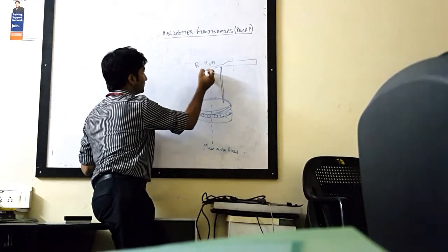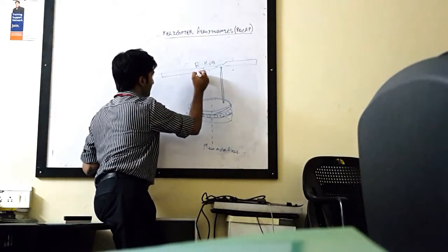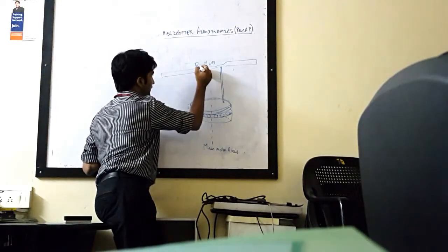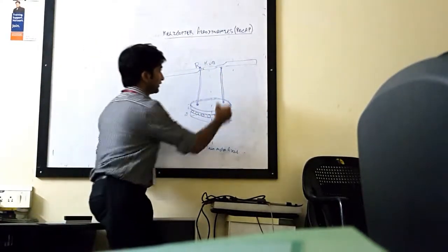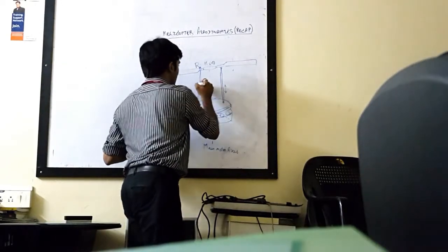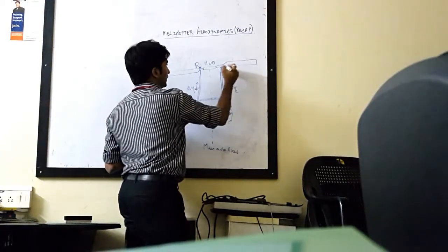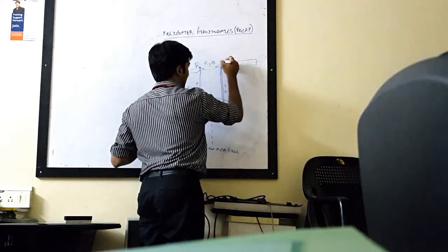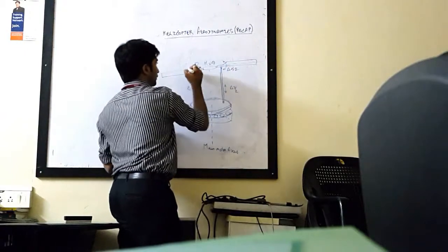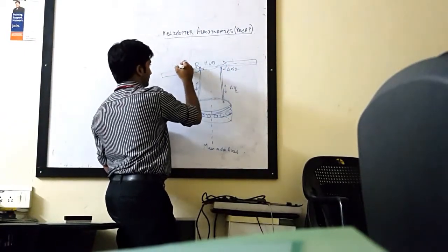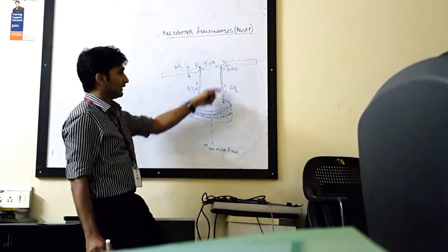So now you also have a similar blade on this side. You have another control rod, okay, which can move up or down by delta y1, delta y2, and it can induce a pitch change of delta alpha 2 and a pitch change of delta alpha 1. Okay, now these are the pitch changes introduced by these particular control rods.